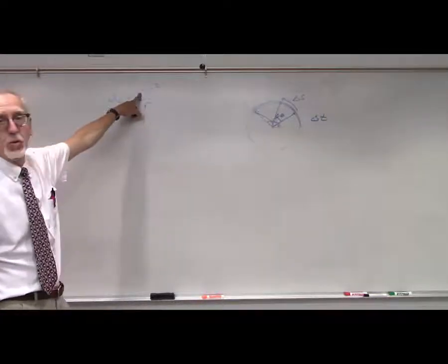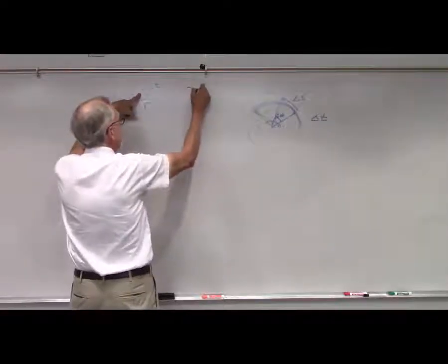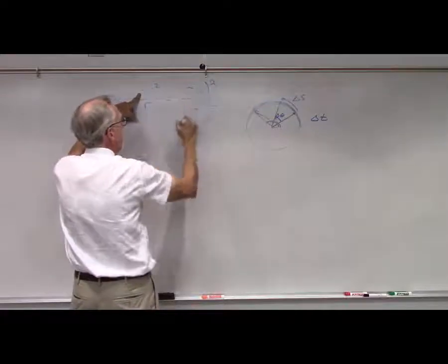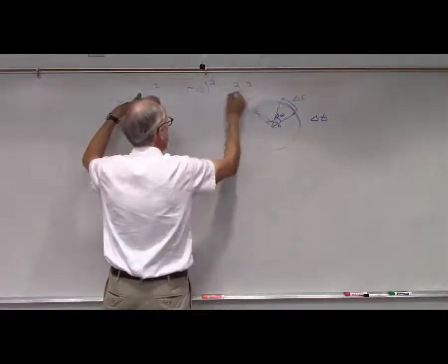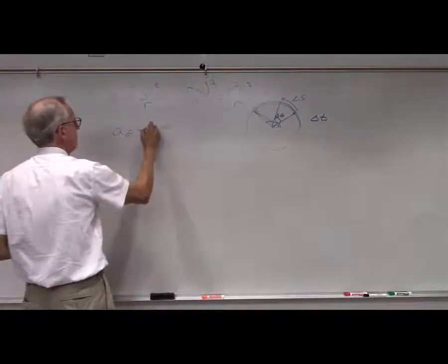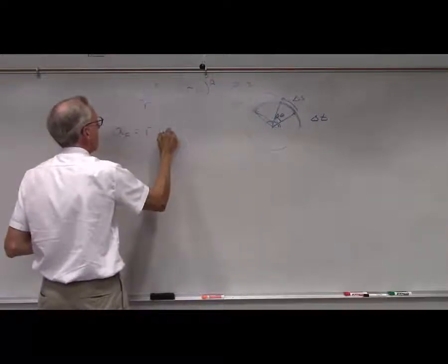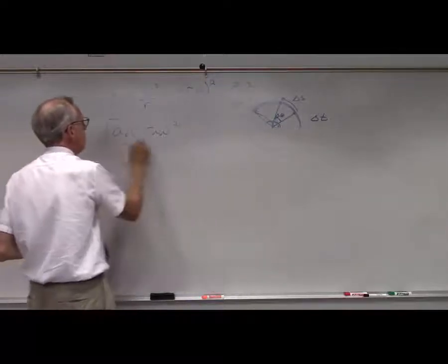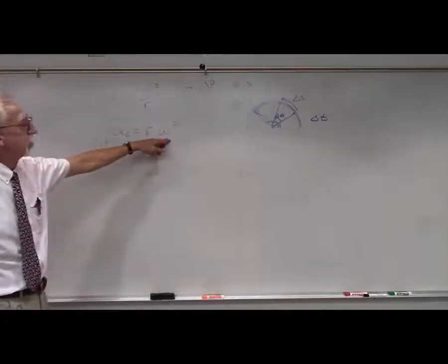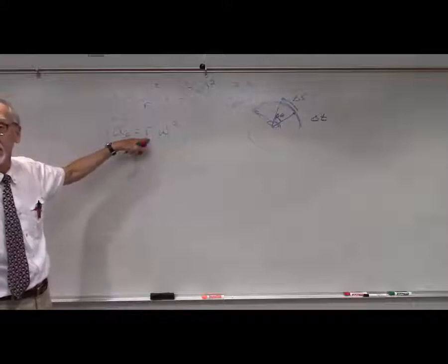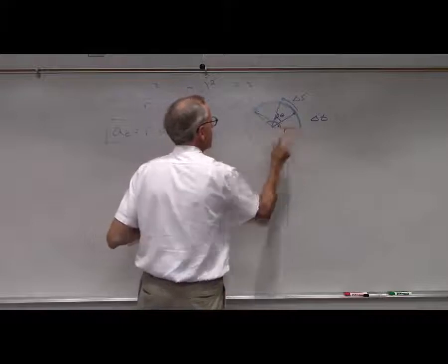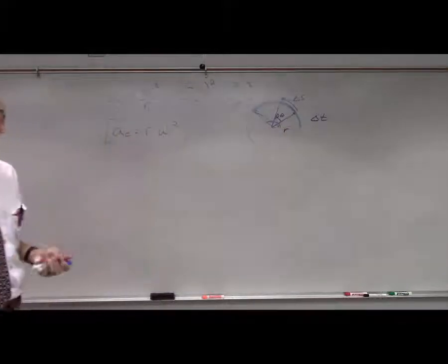Well, if v is equal to r omega, we can write this as r omega squared, there's the linear velocity, divided by r, or r squared omega squared over r, or the centripetal acceleration is, one of the r's cancel, r omega squared. So we have a very simple relationship for the centripetal acceleration in terms of the angular velocity and the radius of the point in question. So remember, the radius r is whatever the distance is from the axis of rotation to our reference point.